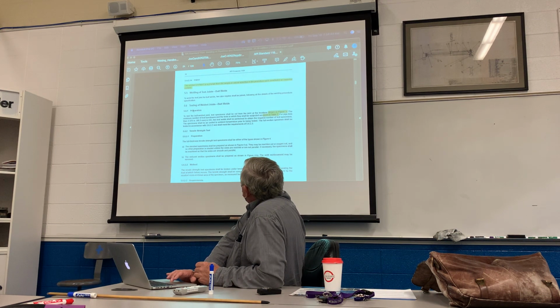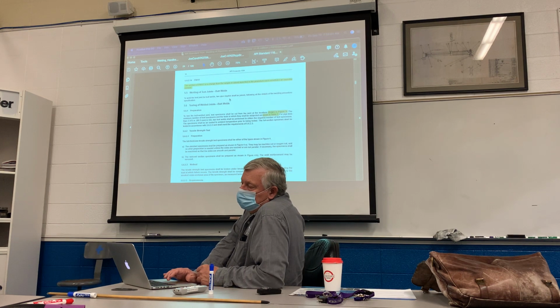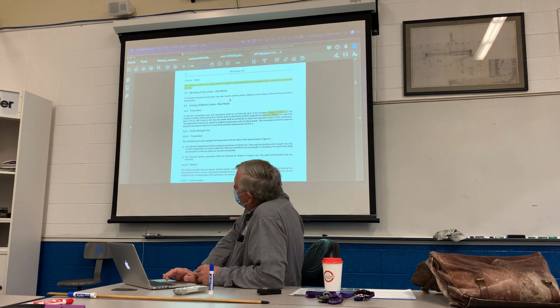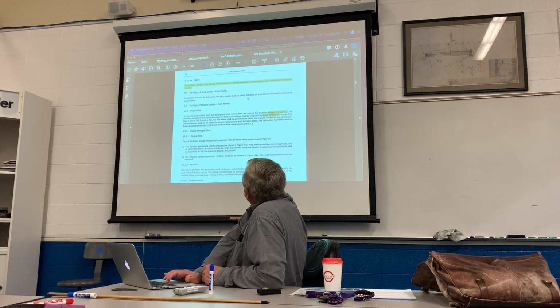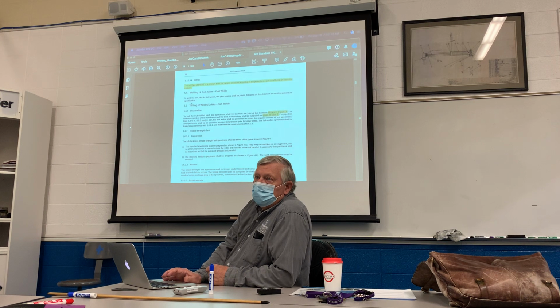Okay, all right, now, the welding of the test joints for butt welds. To weld the test joint for butt welds, 2 pipe nipples shall be joined. That is an appropriate name. Nipple is a really appropriate term. Shall be joined following all the details of the welding procedure specification. So if you got an argument with some pipe boss or somewhere like that, you just refer to that.